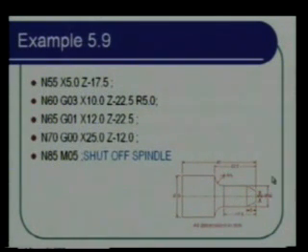So what we are going to do is think of X and Z motions going along the path. Now one assumption that I have made at this point is I ignored the tool nose radius. I am assuming that tool nose radius is 0. But in real practice, tool nose radius is going to be a finite value, and then you will have to offset the tool path by an amount equal to the tool nose radius.